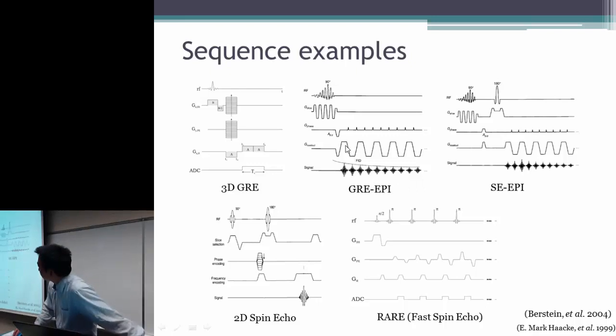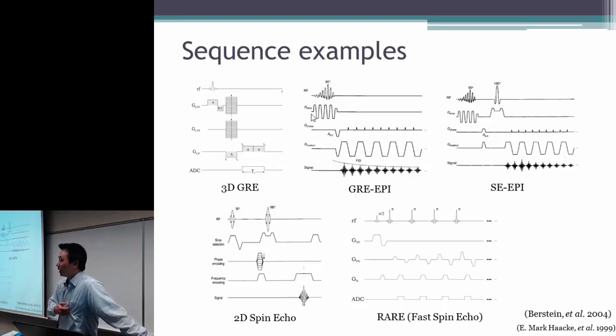I'm sorry? What is the significance of this special RF pulse? Okay, so this one is actually called a spatial selective gradient. Usually, if we use a single sinc pulse by itself, it's spectral selective, right? It has a certain frequency, and when combined with the gradient, it now becomes spatial selective. When we do this, it is still actually a relatively wide band frequency, so its bandwidth is quite wide. So it will excite, for example, both the water and fat.